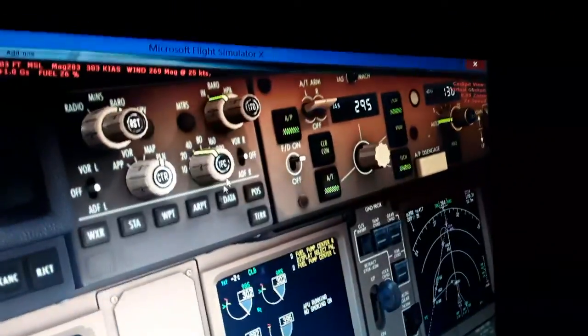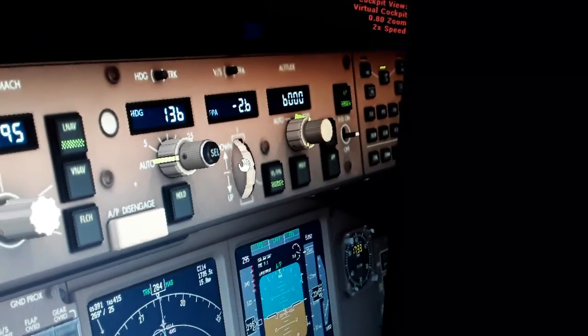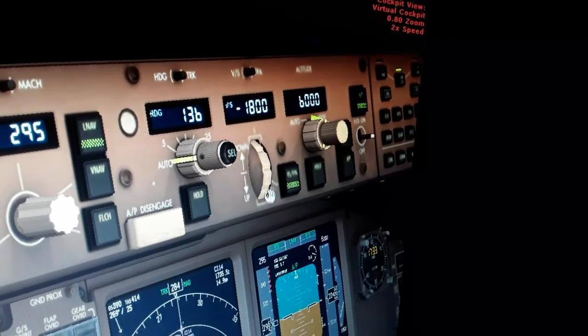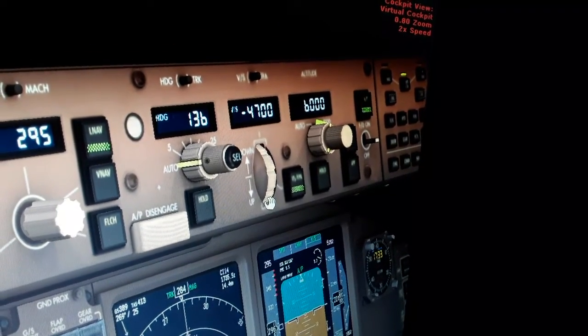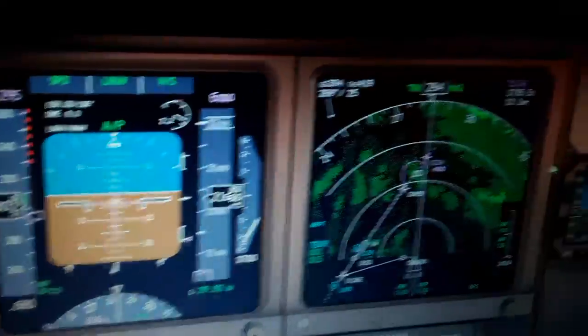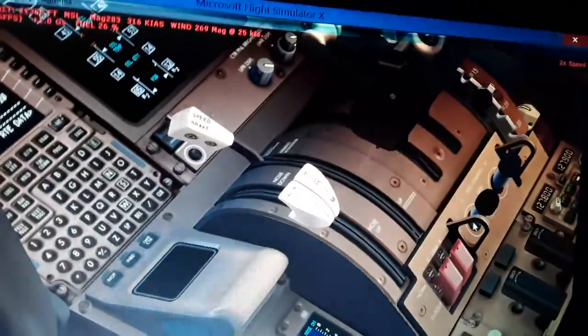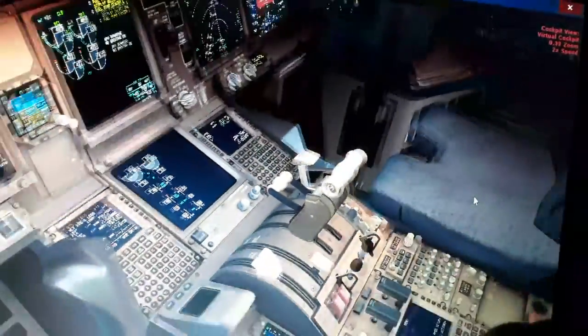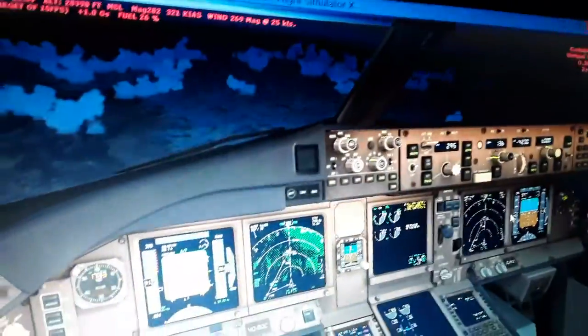33,000 feet, coming closer into the airport, so we get the VS here. It's going to descend faster now. It is over speed, so we need to extend the speed brakes now to slow us down. You can see the autothrottle here for the switch.